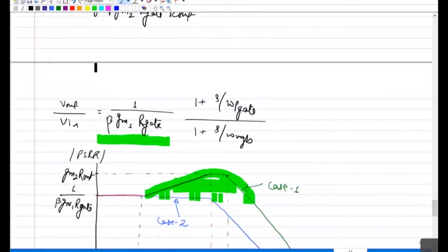and we want this Vout by Vin ratio as low as possible. So that's why most of the time your PSRR in terms of dB is negative actually. So when it increases in negative, that means your PSRR is improving. And when it is reducing in negative or increasing in positive, then your PSRR is degrading actually. So don't get confused with the term like high PSRR, then more negative means it's lower, not higher. Sometimes people get confused with that actually.